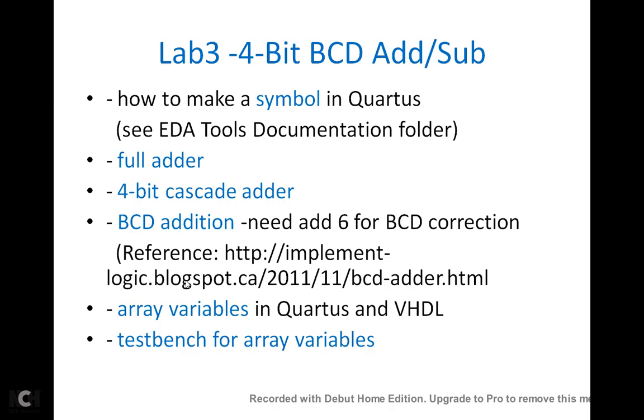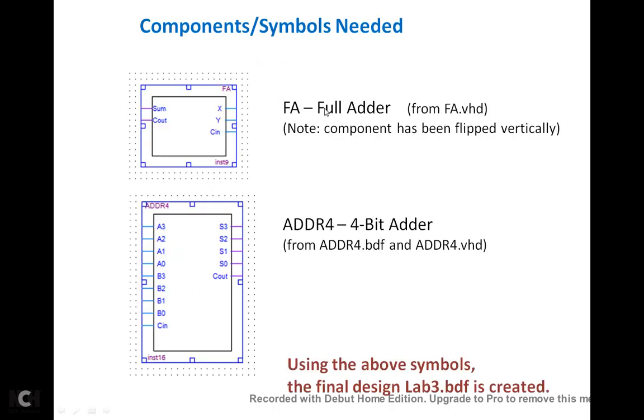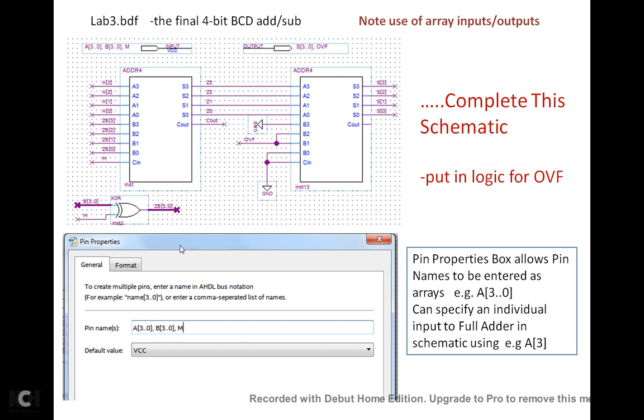So first, we have to create the full adder symbol. Then we have another schematic. Okay, and we put 4 of these full adders, hook them up, and then we turn that schematic into a symbol. Okay, and then we have how many schematics? We're going to have even one more schematic, your final schematic. So there's going to be 3 schematics.